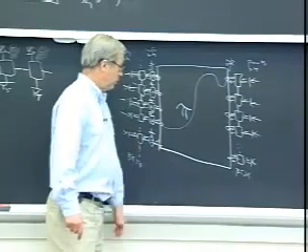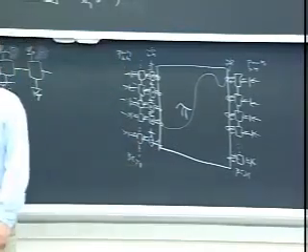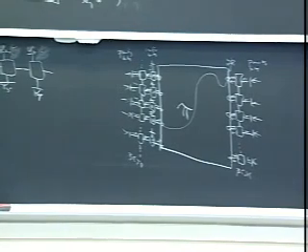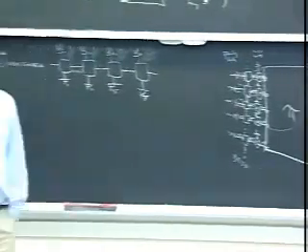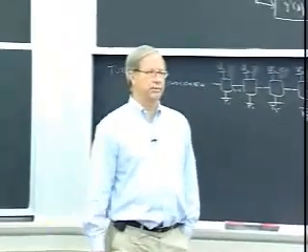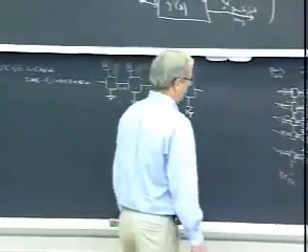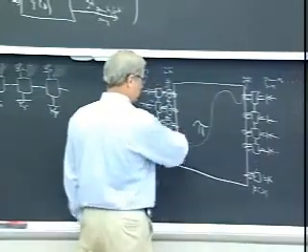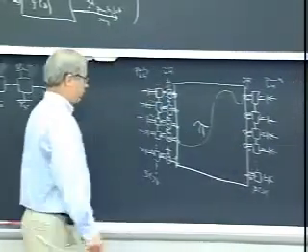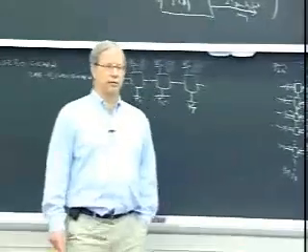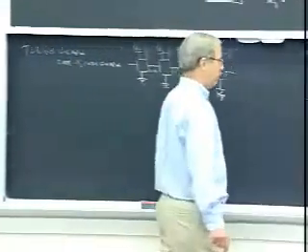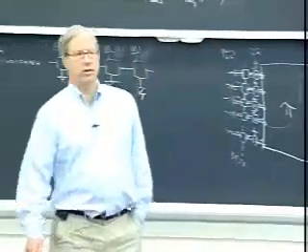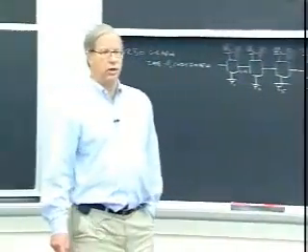So for turbo codes, typically they only do 10 or 20 iterations. Whereas for low-density parity check codes, one does hundreds of iterations, of much simpler iterations. But in either case, you've got to deal with the fact that as you get up in the number of iterations, you are getting to the region where cycles begin to have an effect, where you are reprocessing old information as though it was new independent information. This tends to make you overconfident.